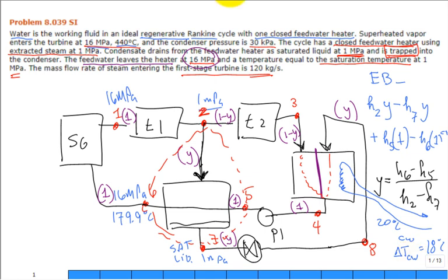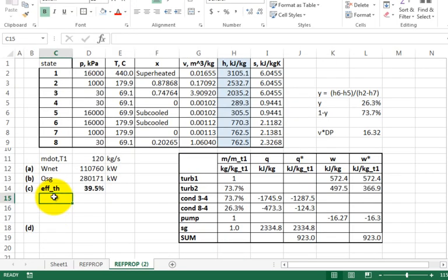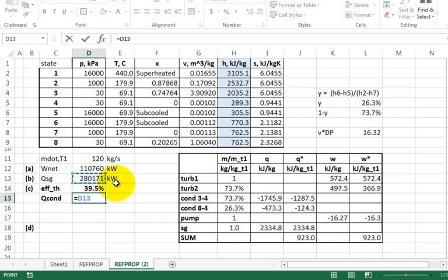Well, what you typically do is break it into steps. What is the Q dot that has to be rejected in the condenser? Can you calculate that? Let's jump back to my Excel sheet. So maybe I say, what is the Q dot rejected in the condenser? There's a couple ways you could do it, but would it be, hey, all this energy that came in minus what went out in work?